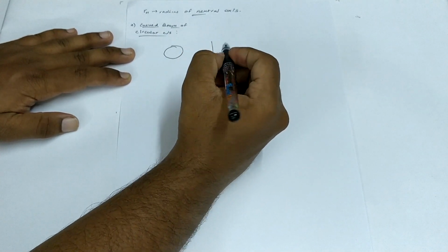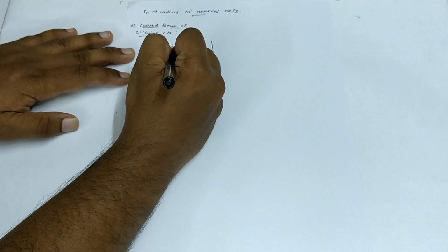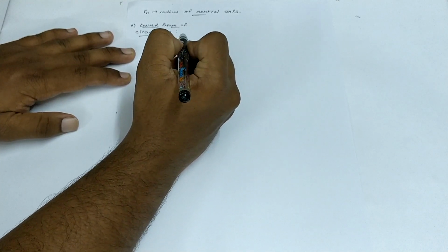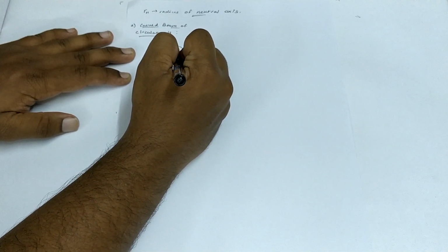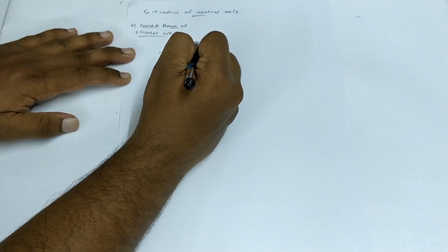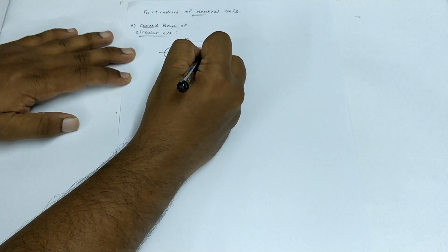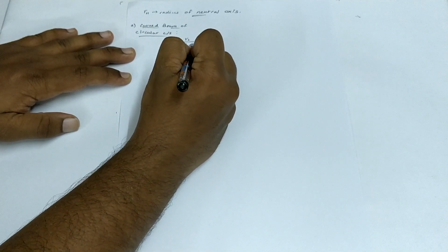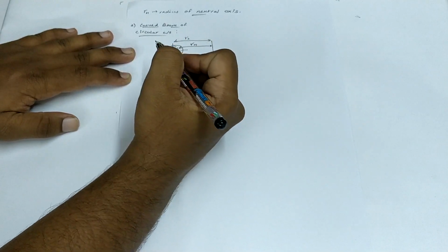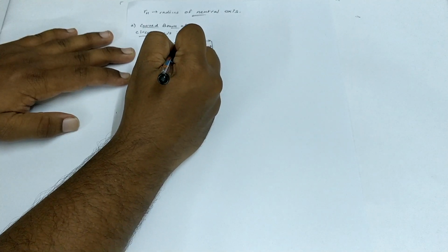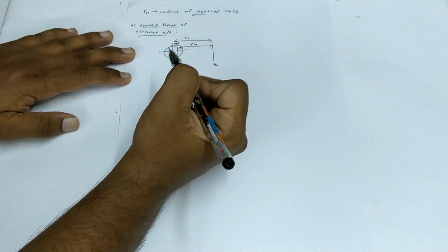First we draw the center line, and we can see that from the centroidal axis to the center line the radius is given by RC. So RC is nothing but the radius of the centroidal axis. The neutral axis, which is below the centroidal axis, has a radius of Rn. The distance between the centroidal axis and the neutral axis is given by E.